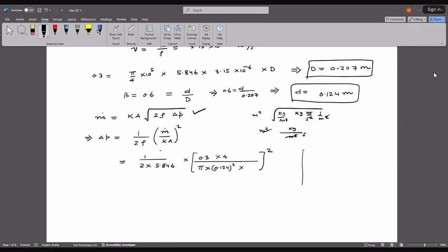If I ask this question, I will actually give you the flow coefficient value. But here we had gone through this plot in the class, which relates flow coefficient K with Reynolds number. It will have a value from 0.6 to 0.8, and depending on the value of beta, these curves will go something like this.